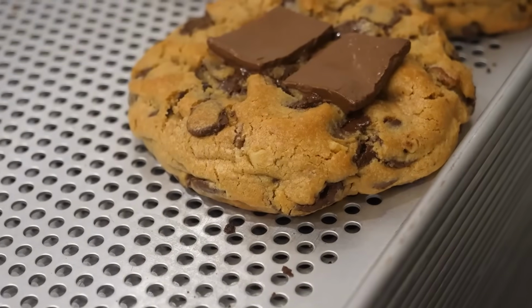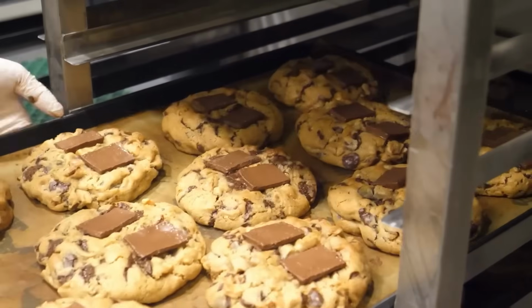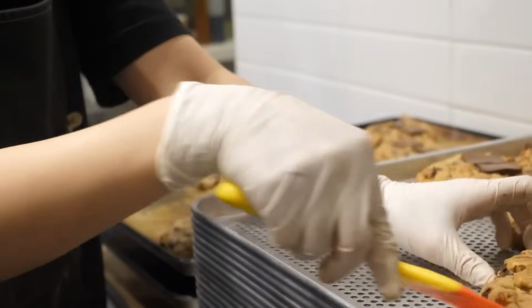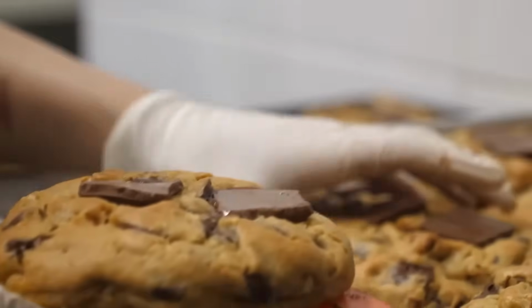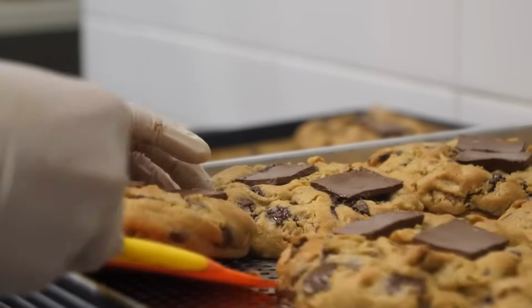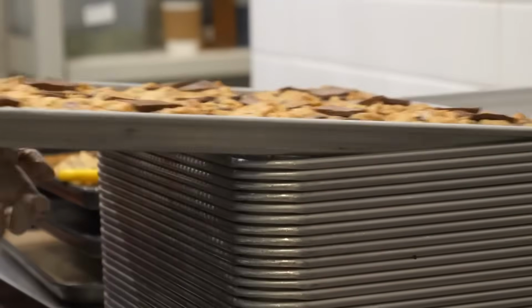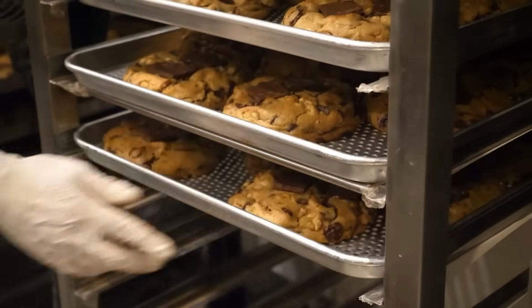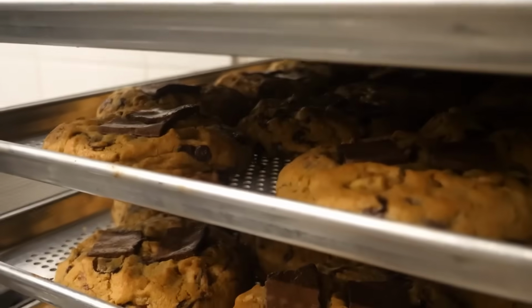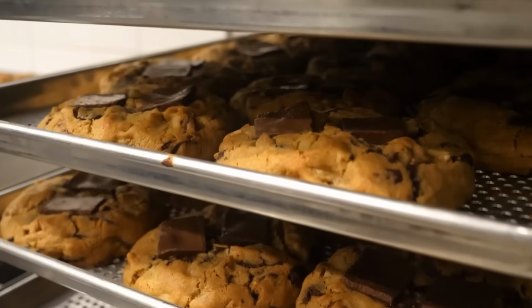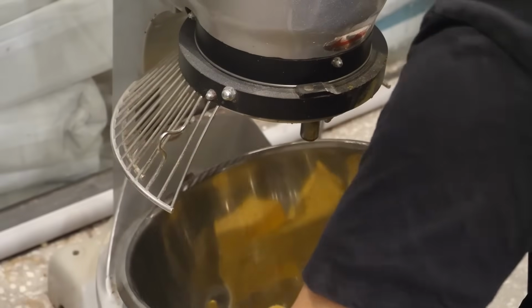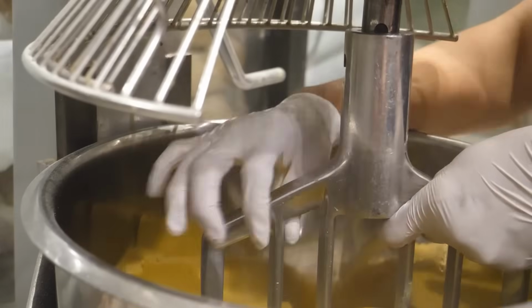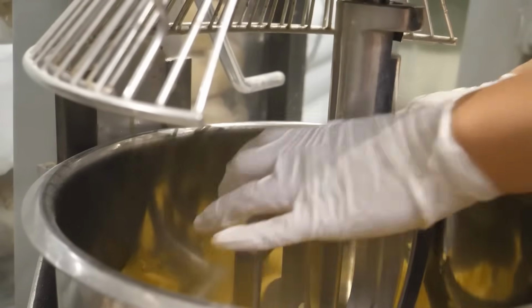This redistribution affects final texture. A cookie that feels soft when hot can become crisp after cooling as moisture equilibrates. For soft cookie styles, the process may include a rapid cooling step that limits moisture loss. For crisp styles, the process may include extended cooling with dehumidified air to drive moisture lower. Air humidity control matters because cookies can absorb moisture from humid air and lose crispness. Cooling tunnels therefore often use conditioned air.